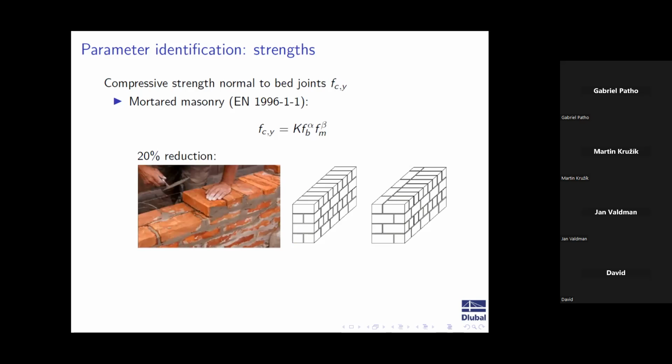So these are the solid blocks, what everybody has seen and used. These are not really used anymore. This is why we call these old style masonry. Nowadays, you have one block per wall thickness. However, here you have some layers with two masonry units, and above that perpendicularly you put one unit.